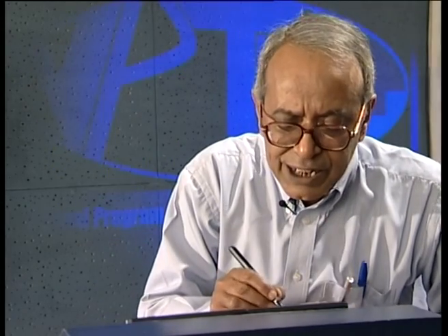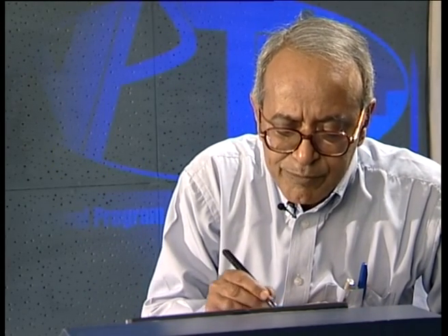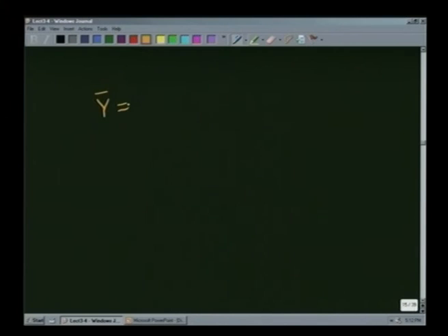Consequently, what we get is that vector y is AB by AD into e to the power I alpha, which we take common, and we get AD plus CB, which is same as O2A, and AD plus O2A is nothing but our vector x.